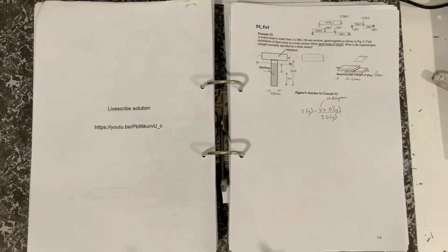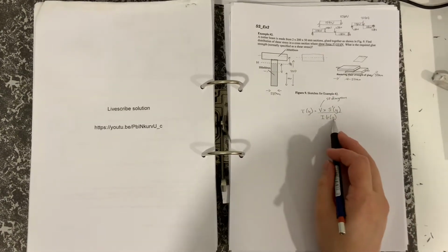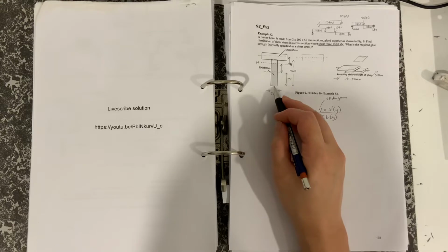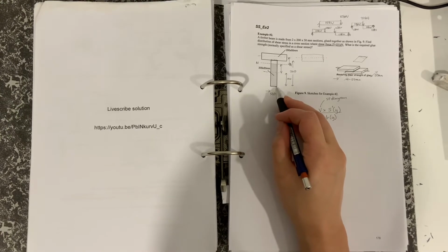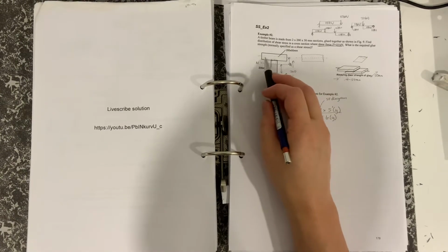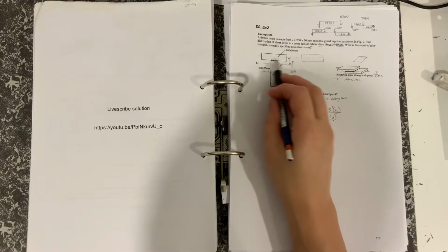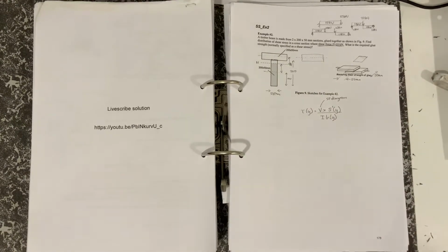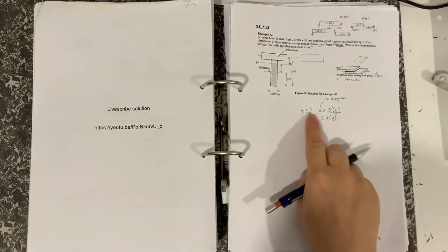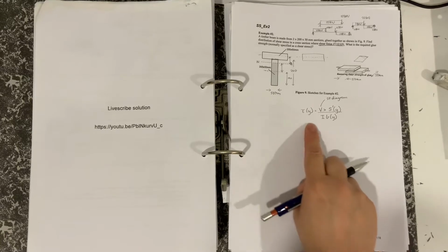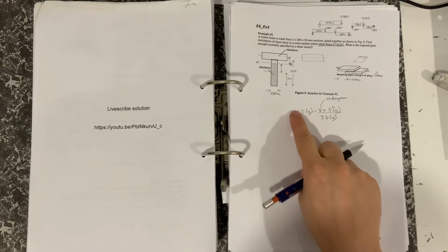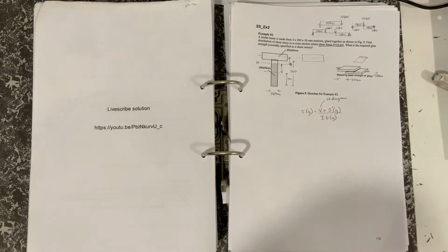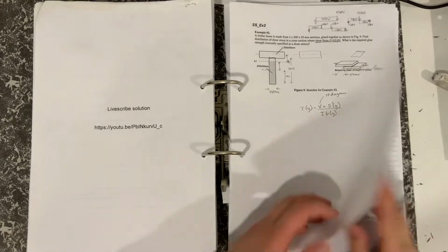There is going to be a jump because this B changes from 50 below the glue. Suddenly it changes to 200 above the glue. So there is going to be a jump. So you should have enough information now to be able to solve that, and to be able to draw the distribution of the force in the glue.